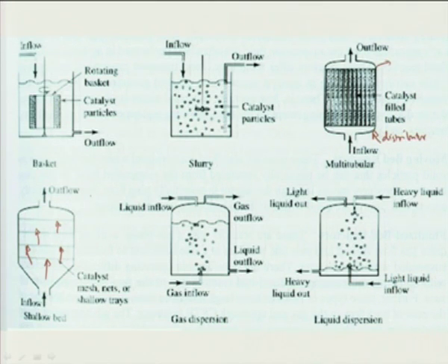So these are the moving bed, or sometimes called spouted bed reactors. These are like the family members of the fluidized bed reactor itself. However, the velocity of the fluid motion is relatively small. Then there are thin or shallow bed reactors in which the reactant fluid flows through catalyst mesh or thin beds, and these are suitable for fast reactions where good control is required over the residence time distribution and temperature. These are quite simple in construction and particularly useful for catalyst reactivation, maintenance and removal of larger heat load.